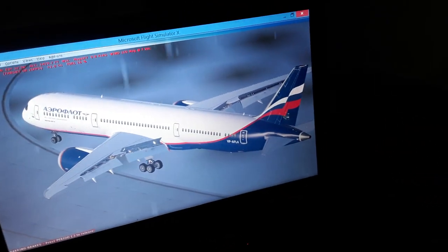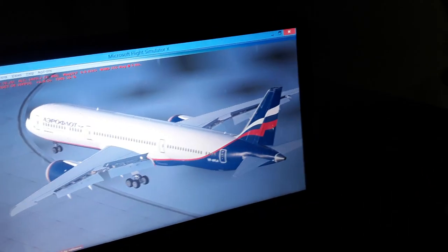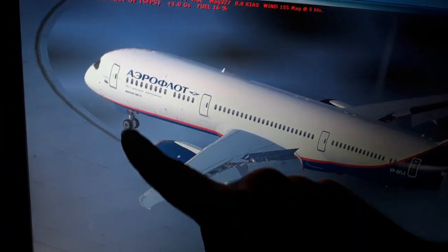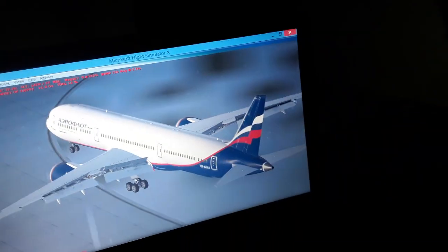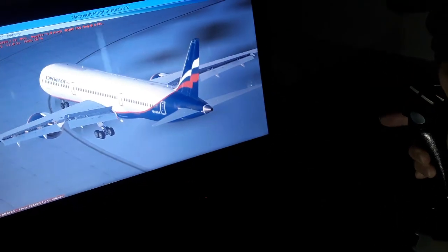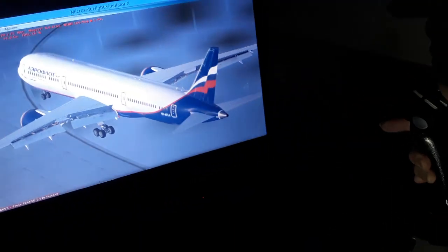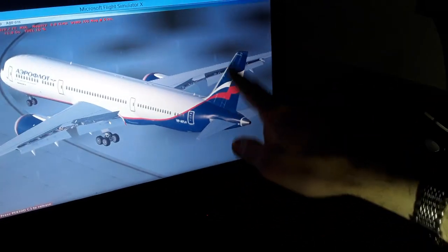Also as we increase the airspeed above 144 kilometers an hour, or about 80 knots, the nose wheel deflects to the zero position. It's locked to zero deflection from the computer. So we have only the rudder to control the aircraft above 144 kilometers an hour in takeoff. Also in landing, the computers do the vice versa. It's the inverse flow. So we have both the nose wheel and the rudder.